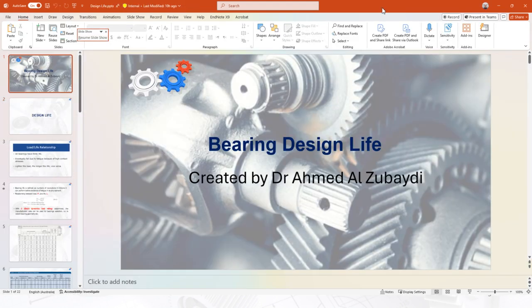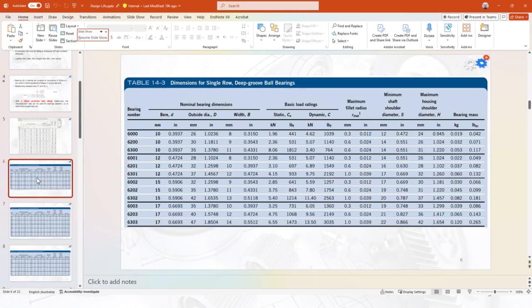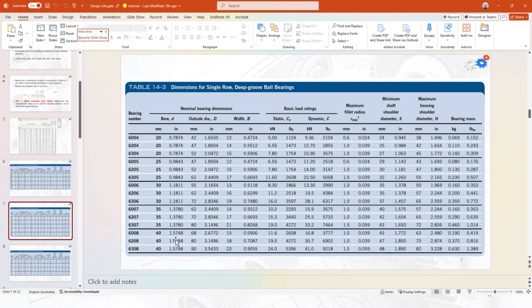So, yeah, we're looking at a diameter of 40 and the load of 29,600. So we're going to go to the table here and look for the diameters. These are the small ones. Now here, we're going to start to have the larger ones. We locate the value for the dynamic C. That's in kilonewtons, that's 16.8. That is the 30.7, which is more than 29.6. So I can choose this one. The diameter is 40, so it's going to be above the minimum value, and I can go with that.